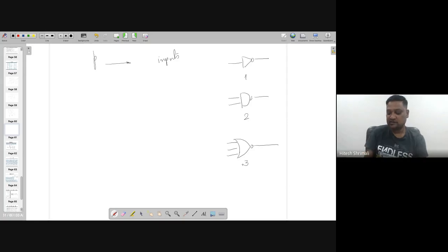Note that all these numbers are normalized with the time constant of a unit inverter. This time constant depends on various parameters of the particular technology, so we are not writing that. However, you have to read it as hidden: the time constant is there, and the unit is right now unitless, but multiplied with time it will become seconds.